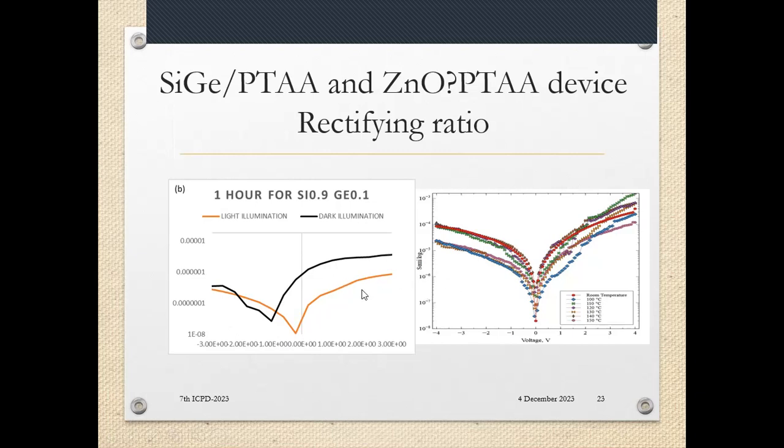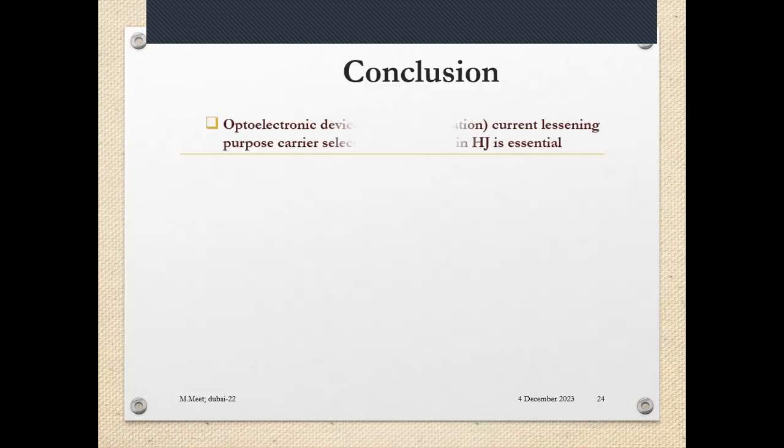and that is ultimately most impactful for the development of photo devices. Because silicon is a well-established microelectronics material also used in optoelectronics, and silicon dioxide is a robust passivation layer that can make this materials technology achieve higher forward current density or higher rectifying ratio. So the conclusion is the barrier height or carrier selectivity is very important.